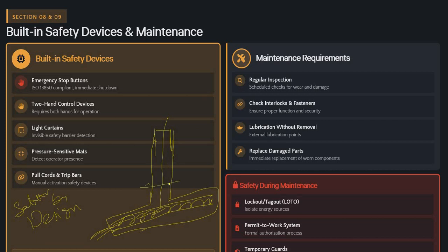So at this level, he is able to place his hand in the screw feeder. But what I did is, I increased the chute height. Even if you try to make contact, it is not at all possible, because the chute height is very big and he is unable to contact this surface. So like that, we need to do safety by design.